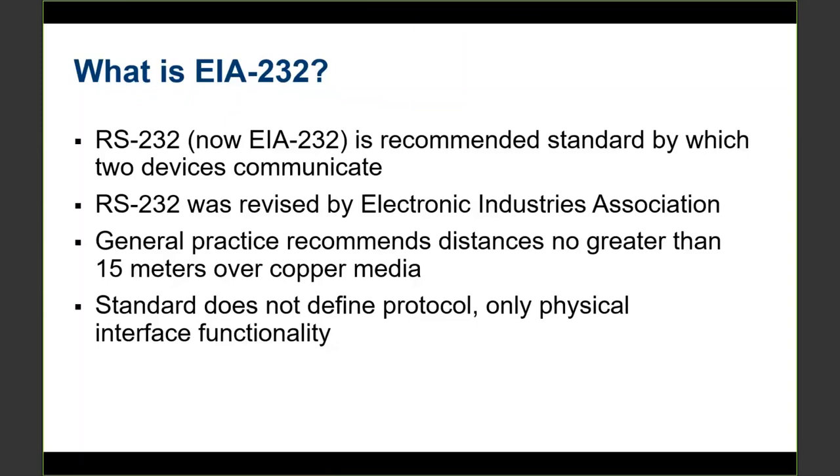Okay. And then the standard doesn't define the protocols that use 232 communications. These just basically define the physical interface functionality. So protocols are independent of the serial communications type, whether it be 232 or 485 or 422.